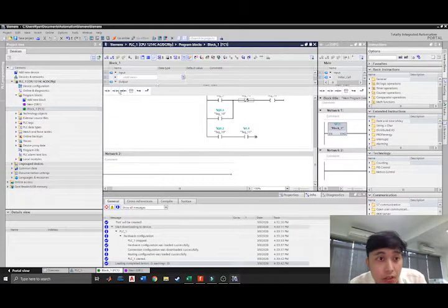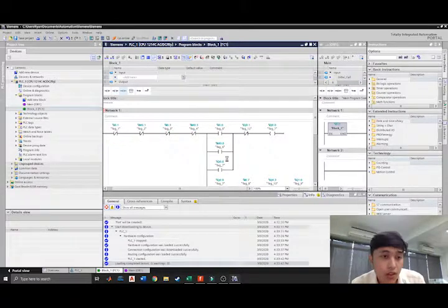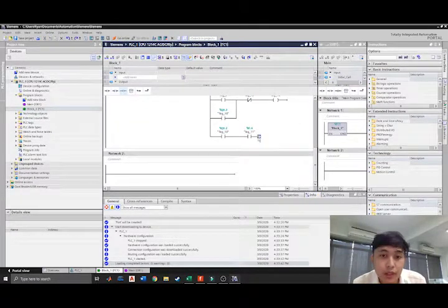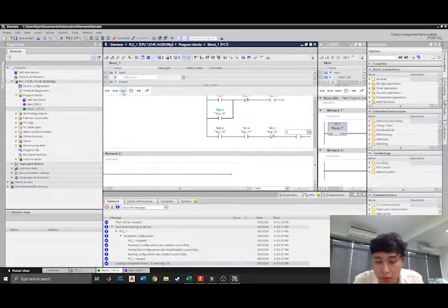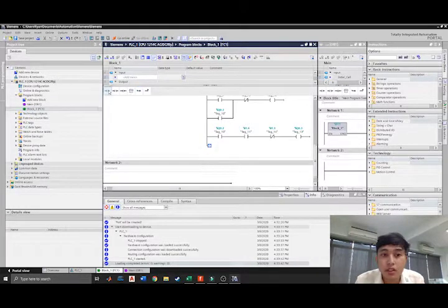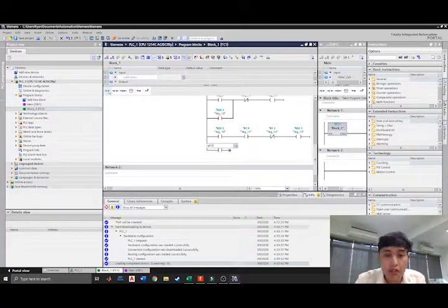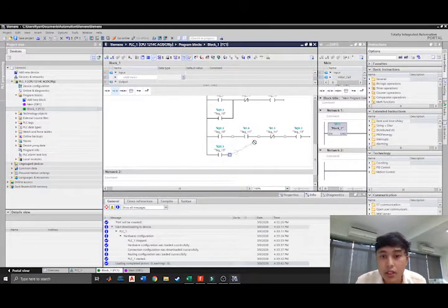Now let's continue. A normally closed contact for the reed switch when the drill goes up, I1.3, and the output is the drill cylinder going up with the address of Q0.3. Then let's place a latch, Q0.3, and connect that here.